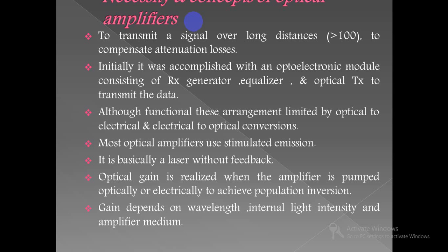Traditionally, when setting up an optical link, one formulates a power budget and adds repeaters when the path loss exceeds the available power margin. To amplify an optical signal with a conventional repeater, one performs photon to electron conversion, electrical amplification, retiming, pulse shaping, and then electron to photon conversion.